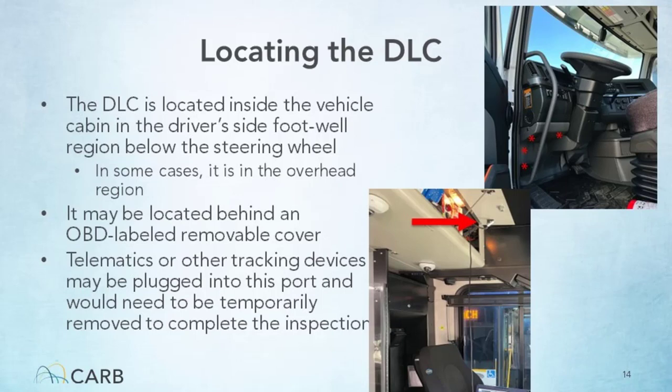In some trucks, telematics or other tracking devices may be plugged into the DLC. These devices would need to be temporarily removed in order to perform the HD-I&M OBD test.